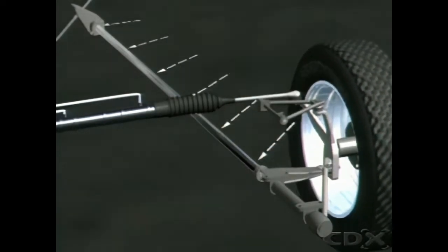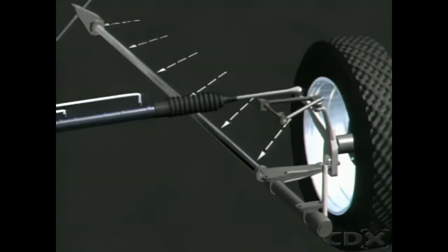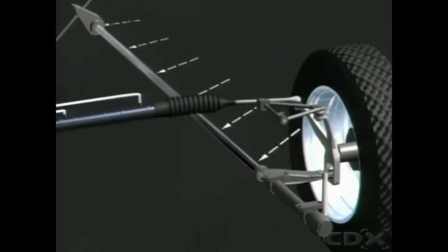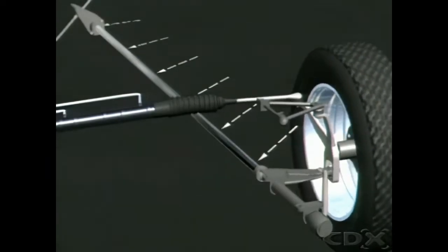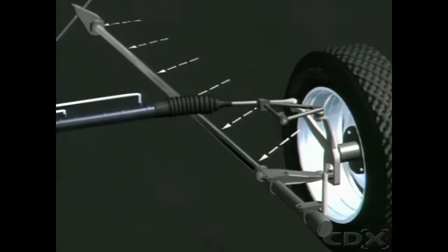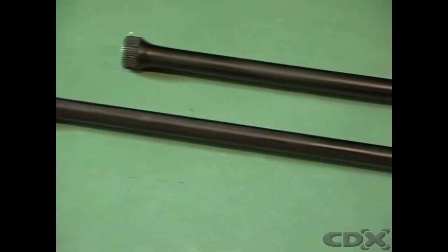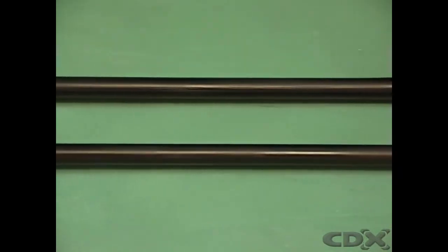When the vehicle is placed on the road, with a control arm connected to the suspension assembly, the bar supports the vehicle load and twists around its centre to provide the springing action. Spring rate depends on the length of the bar and its diameter. The shorter and thicker the bar, the stiffer its spring rate.